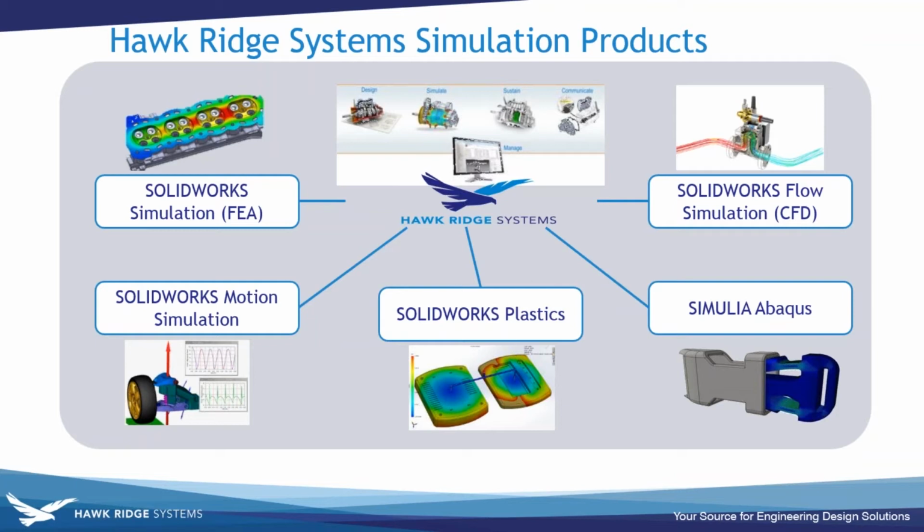Again, all these things are integrated within the same environment of each other, where they'll be able to communicate, export and import different aspects of a study type to get a specific answer. And that's what we're going to focus on today: the Simulation SimPro and the SOLIDWORKS Flow Simulation, where I'll be running ultimately a structural analysis in either a linear static or nonlinear, but being able to transfer the thermal results from a simulation study or from a computational fluid dynamics tool like Flow Simulation.